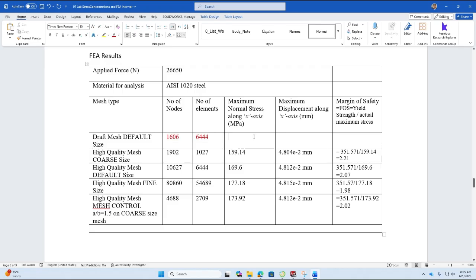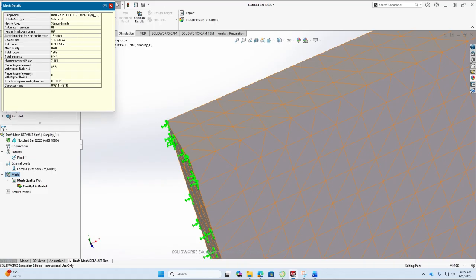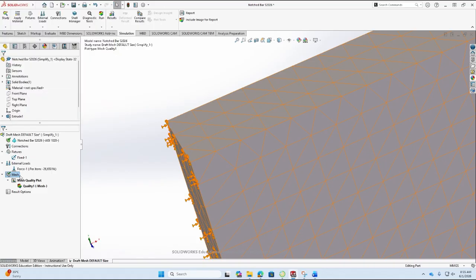It's giving me an error. What's wrong? Mesh information is not current. Model might have been updated or mesh element size tolerance was modified. So maybe you modified it, so just remesh it. Should I delete it? No, just go to create mesh again. Okay, create mesh, and then just select the options. Didn't change anything else, right? Yeah. Mesh.